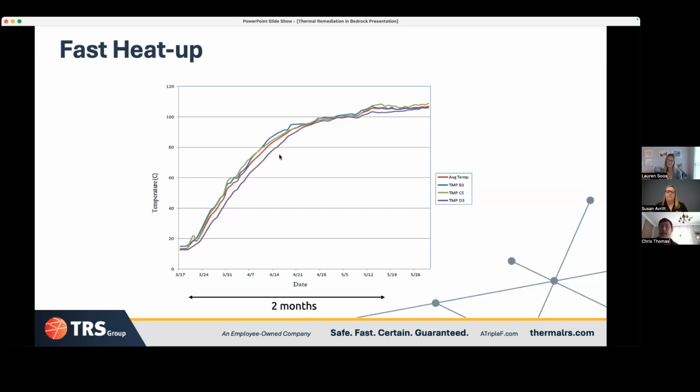And then a couple weeks later, we're up at boiling, and the boiling curve shifts because all these RTDs or temperature monitoring points are located in the hardest to heat areas, but there's boiling occurring close to these electrodes. But this represents the worst case. That matches up exactly with what Susan was showing on her other site. We've got things starting to happen around 70, 80 degrees C, maybe 6 to 8 weeks into project operations. And by the time we get to 8 to 10 weeks in operations, we're generating steam full bore, and mass recoveries and removals are occurring full bore.